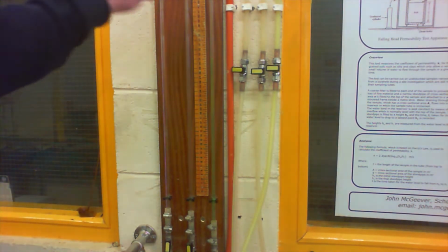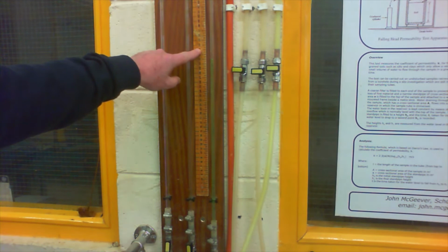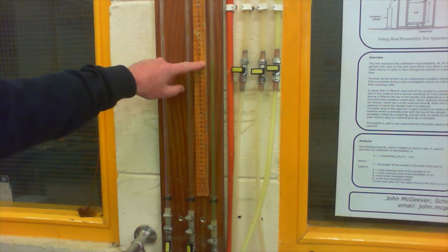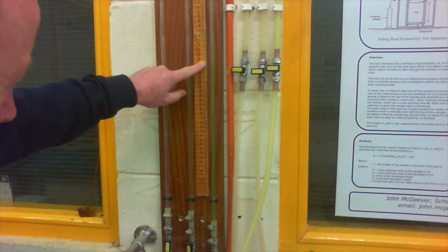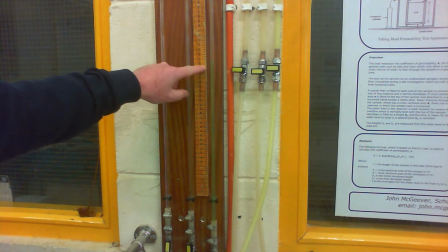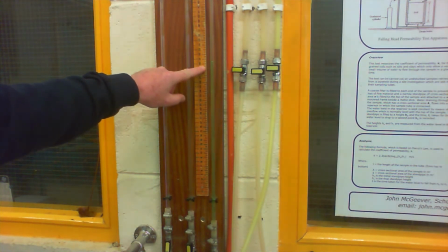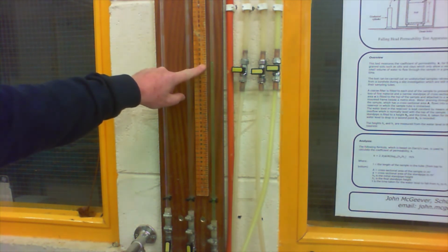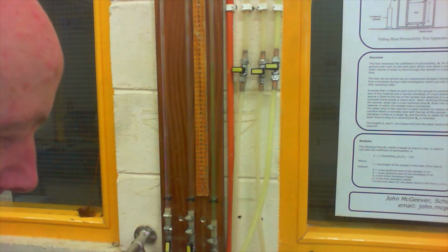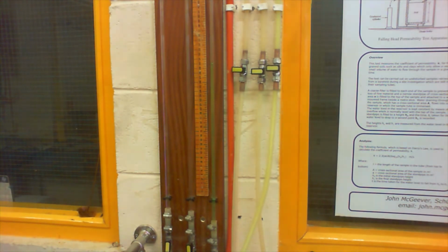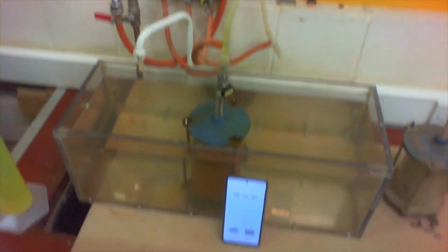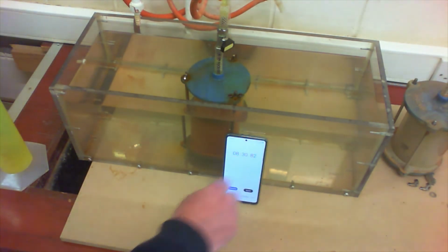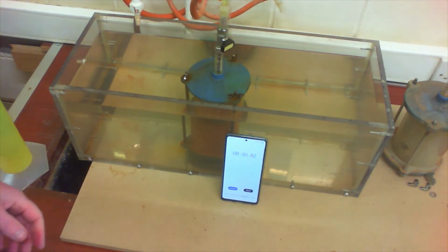Now, the water has been falling in the tube for just over 7 minutes, and we're going to stop the test very soon. The reading on the meter stick is just gone past 31, so I'm going to stop the test when it drops to 30. I think you can see it's dropping very, very slowly, and this is because it's an impermeable soil, not like a sand, for example. So there it is, just reaching 30, and I'll turn off the sample there and stop the stopwatch. And the stopwatch is stopped at 8 minutes and 30 seconds.